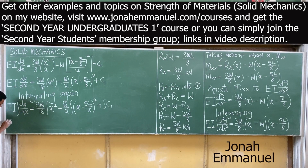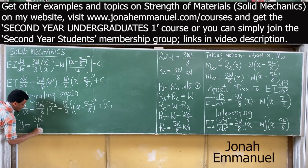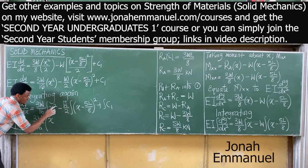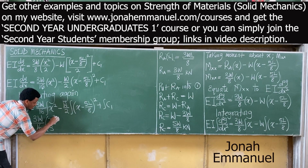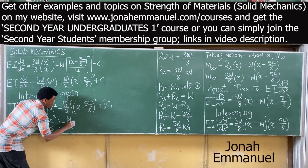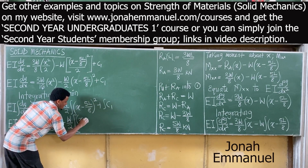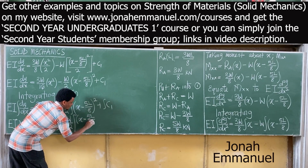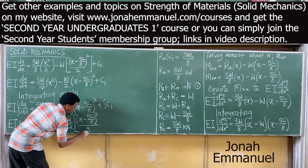From here, I have EI y is equal to, what do you have here? 3W over 16 into x, 2 plus 1, 3, so 3 all over 3, minus W over 2 into x minus 5L over 8, 2 plus 1, 3, all over 3.